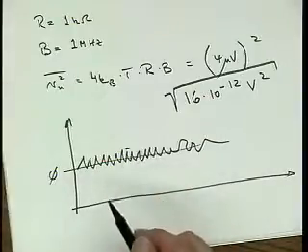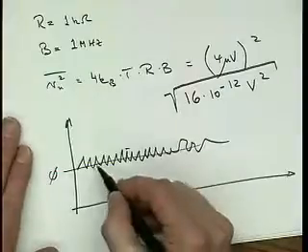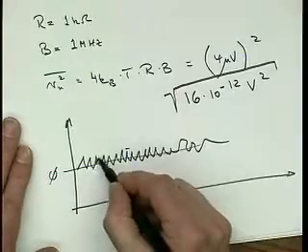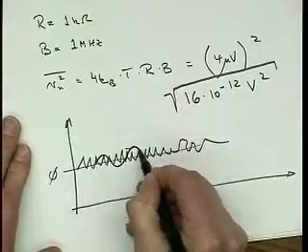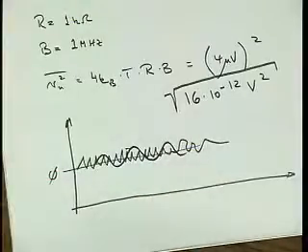Then we put in a sinusoid and adjust the sinusoid's power, using some kind of power meter, so that it is just equal to the power of the noise. Then that sinusoid would be just about equal in amplitude to the peaks of our noise. Sort of the peaks, since we know there's this Gaussian distribution in it. So, okay.